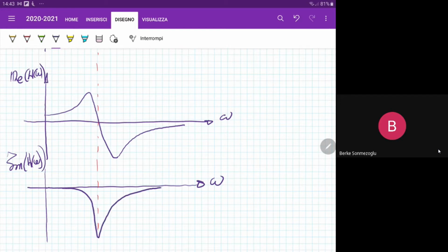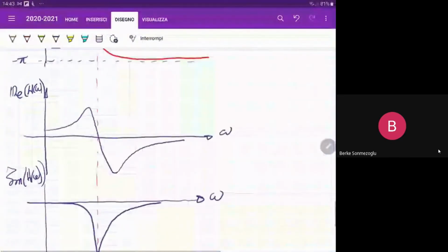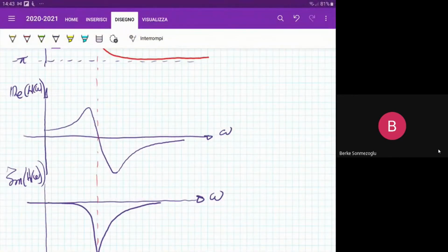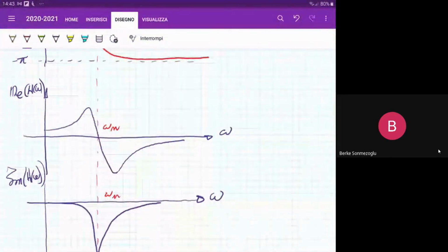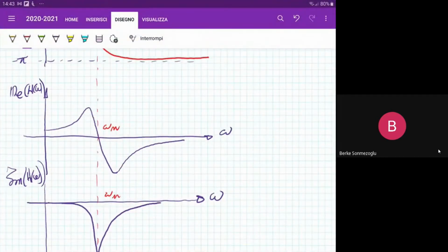As we can see, the real part of your FRF is crossing the zero axis when the frequency of excitation is once again equal to the natural frequency of your system. When omega is equal to zero, we have the flexibility once again, because the real part is the only non-zero part of the FRF, whereas the imaginary part is zero.